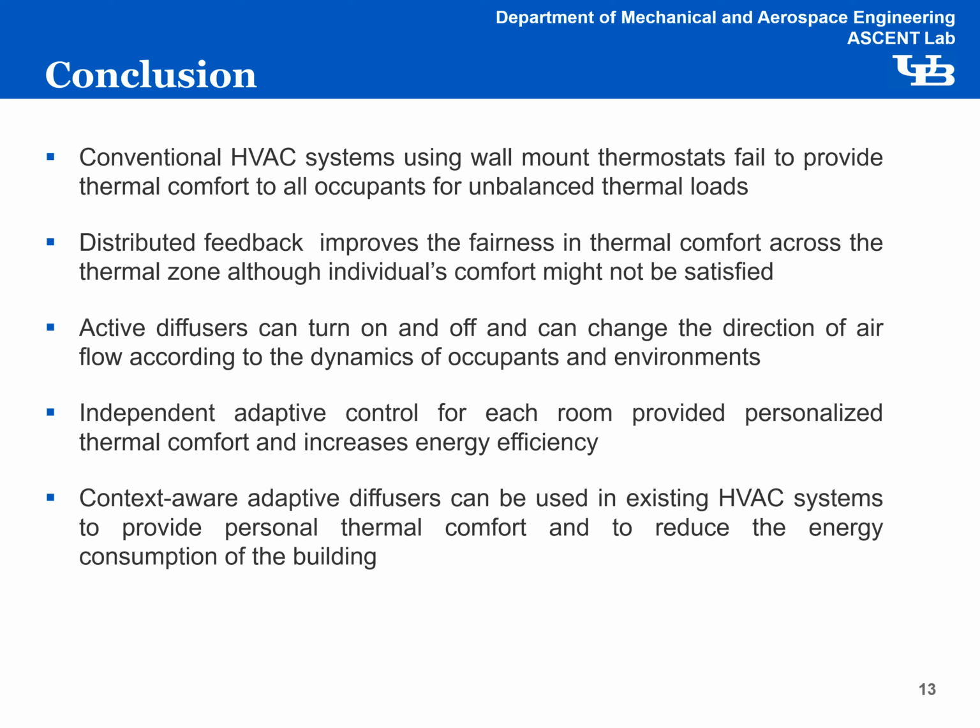Directional diffusers have the ability to change flow direction according to the dynamics of the occupant and conditions in the room, and when independently controlled, increase the energy efficiency of the HVAC system. These strategies can be adopted by buildings to decrease energy consumption without replacing their existing HVAC systems.